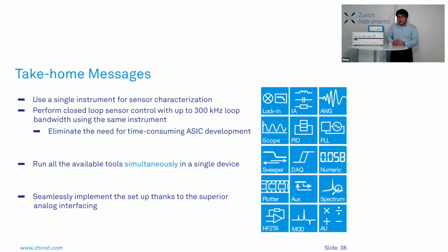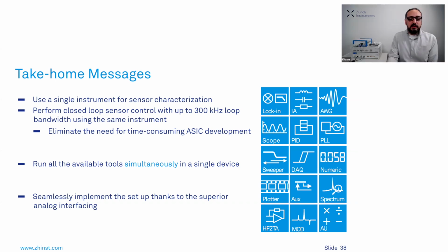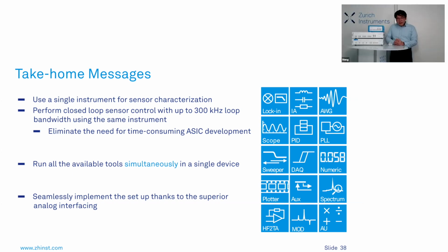So the first question actually is coming from the previous section. One attendee asked, you mentioned your lock-in amplifier can measure from DC. How is that possible? How good is the DC measurement? I see. So these instruments indeed can work from DC to their bandwidth, like 5 megahertz. So basically you can measure by setting the oscillator at 0 frequency, and it's still possible. I hope this answered the question. Meng, you think? Yes, that's actually a very good answer.